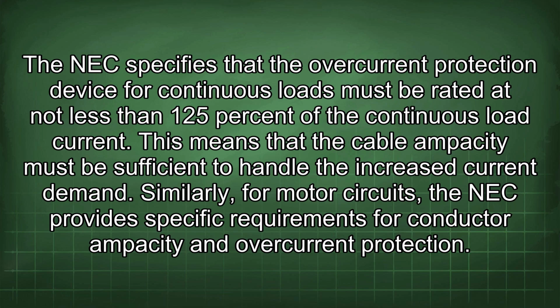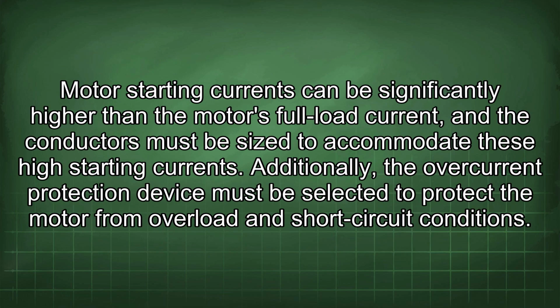Similarly, for motor circuits, the NEC provides specific requirements for conductor ampacity and overcurrent protection. Motor starting currents can be significantly higher than the motor's full load current, and the conductors must be sized to accommodate these high starting currents. Additionally, the overcurrent protection device must be selected to protect the motor from overload and short-circuit conditions.